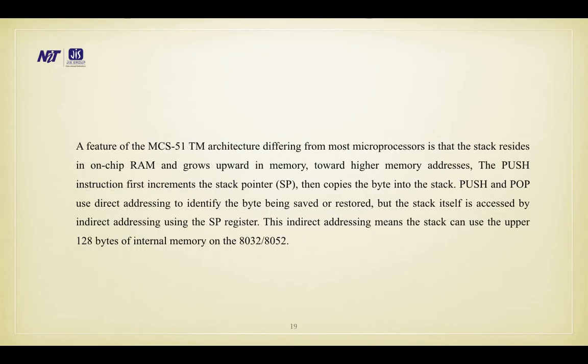A feature of the MCS-51 architecture differing from most microprocessors is that the stack resides in on-chip RAM and grows upward in memory toward higher memory addresses.